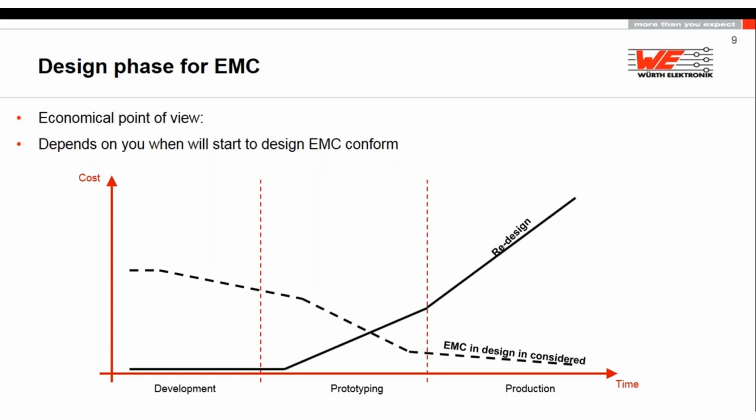Many people say we don't have space. Okay, there's always a way. 0201 size, maybe it's difficult to solder by hand, but sometimes there's space for 0603, or some people can even solder 0402 by hand, but I would definitely go for 0603 or 0805.